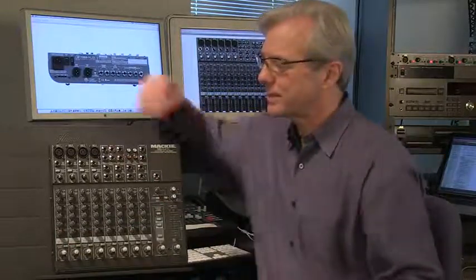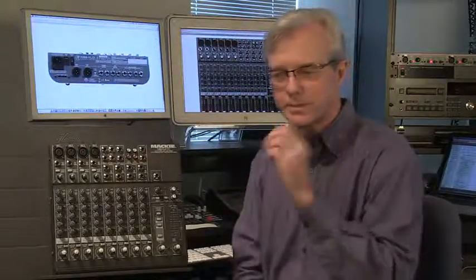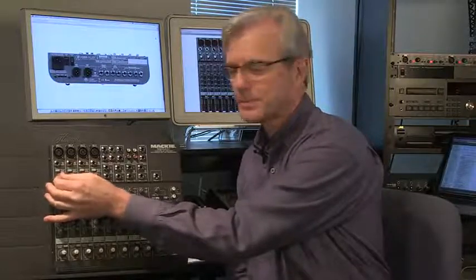And usually when I hear recordings where there is some kind of noise to the sound, it's often that the setting for the preamp is not exactly correct. If you set the preamp too low, then you don't get enough signal coming in so that you end up having to raise the output level much higher to get the correct balance. And then you get noise on that end. So what you want to do is try to get your preamp signal as high as you can without getting distortion. And that's where you have to check to make sure you record the sound and test it to make sure that it doesn't get too loud and cause distortion. And that's, I think, in some ways the most critical part of the mixing, getting the right preamp set.